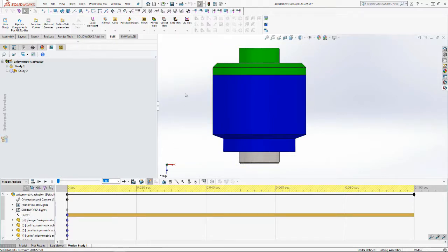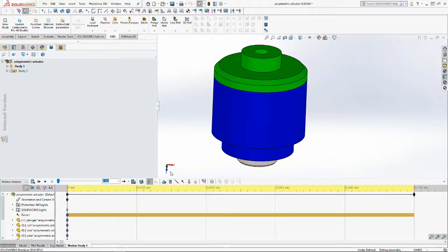In case we want to couple a basic magnetic simulation to a motion, we have the option to define a force or motor, or a rotary or linear motor. So if we define a force and we want EMS to compute the force, then send it to SolidWorks Motion and get the displacement from that. Or we move something and compute the results. It's like parameterization. If we want to rotate or translate something, at each position EMS computes the force.